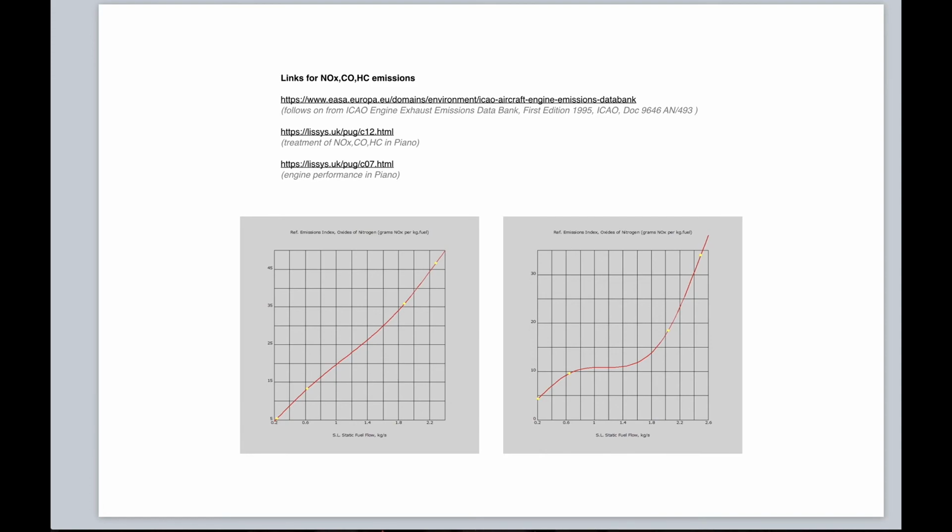Regulatory data are only published at 4 thrust settings at sea level. They are extrapolated to in-flight conditions throughout the industry via a simple set of corrections known as the Boeing 2 method. Because only 4 regulatory points are given, and because such points can be very irregular, the practical usefulness of the data is limited and potentially vulnerable to gaming.